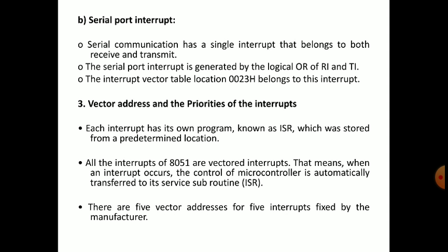Now the vector address and the priorities of the interrupts. Each interrupt has its own program known as the ISR, interrupt service routine, which is stored at a predetermined location. That location address is the vector address. All the interrupts of the 8051 are vectored interrupts.